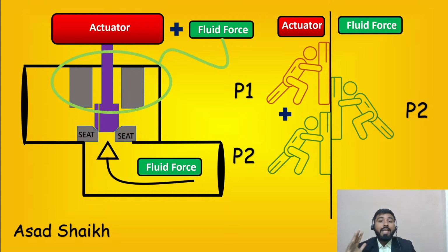Even if you take a class 6 shutoff, it will definitely not have the capability to actually shut off, because at higher DP, for example 30-50 bar, your valve is definitely going to leak. So what I suggest as a solution is, it is costly, but if you need very high shutoff, have a control valve and at the downstream have an actual on-off valve. Ball valves or gate valves have very good shutoff capabilities, and they are predictable. Once you shut off, you definitely know it is going to be shut off.